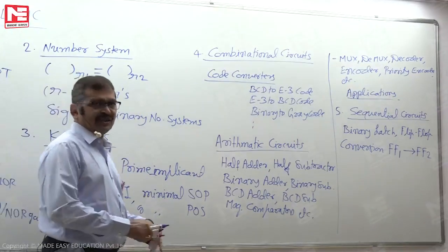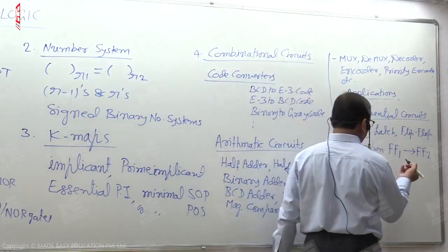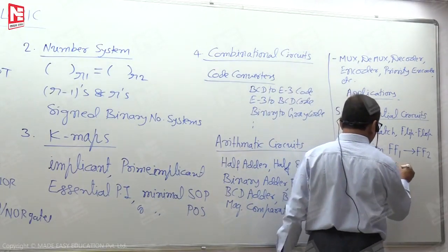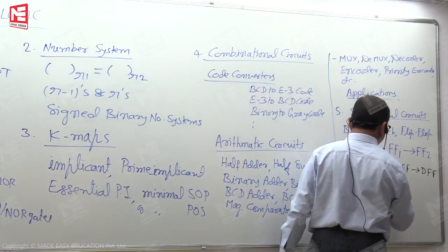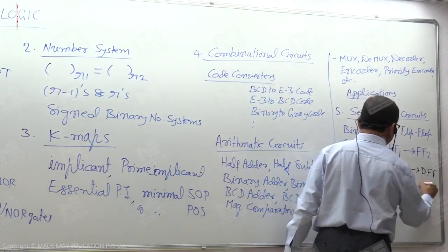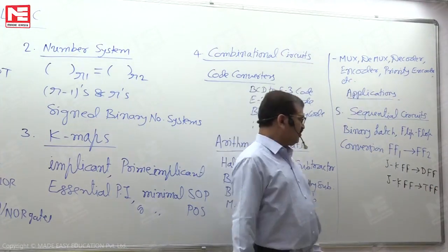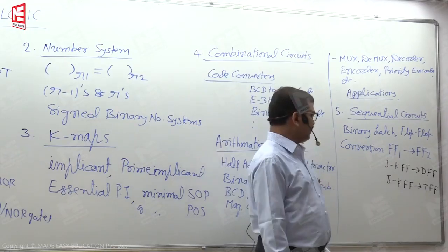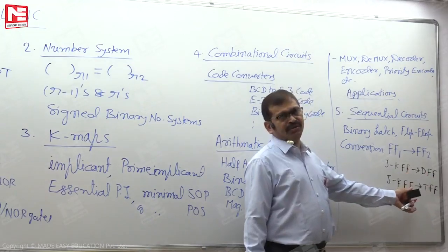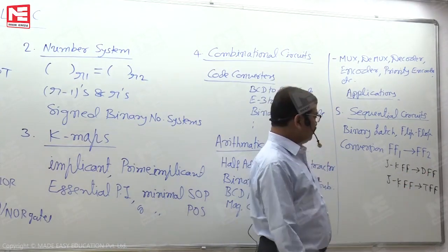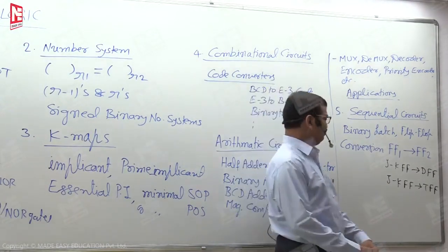In this conversion work, we are not limiting ourselves to only a few standard things, just JK to D or JK to T. We need to know even the reverse: whenever we have a D flip-flop, how to convert it to JK, or to T. More generically, we need to learn how to convert a flip-flop 1 into a flip-flop 2.